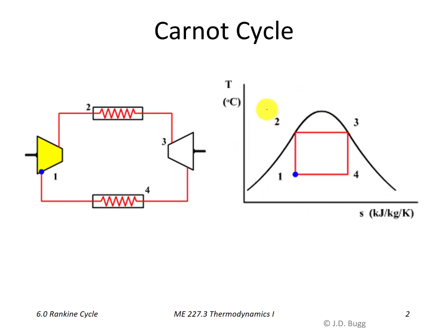So if we look at our TS diagram here, this is the same starting point as for refrigeration systems, only now we're going around this in a clockwise direction, which is the same way that we originally introduced the Carnot cycle. So we have here our reversible adiabatic compression, constant temperature heat addition, a reversible adiabatic expansion, and finally constant temperature heat rejection. So those same 4 basic Rankine cycle processes. And in addition, for a Rankine cycle, all 4 of these processes are reversible. So 2 constant temperature, 2 isentropic. So it's a rectangle on a TS diagram.